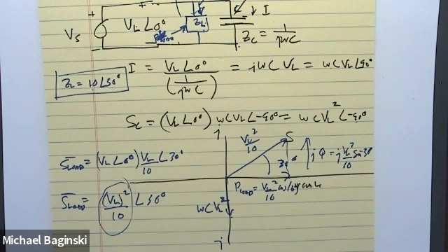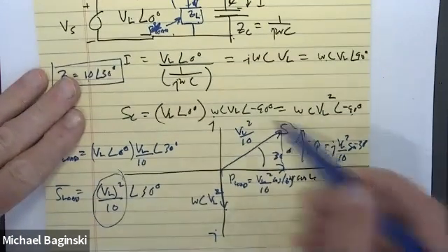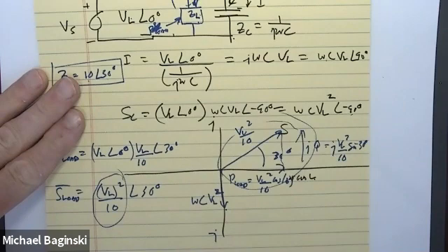I've got two complex powers: one of the capacitor that's strictly minus J, and one complex power associated with a load, a fictitious load, but an inductive load. I plotted them. The sum of these things equals the total complex power. Do you all hear me? Now, when I draw the final one, this is, by the way, called a power triangle. If you ever hear that term, that's what they mean. They show reactive and real power drawn like this for any system.